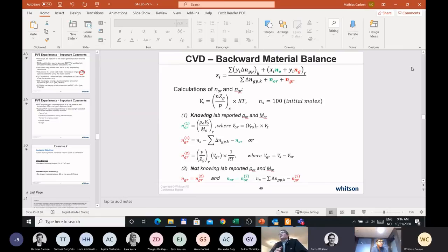So as soon as you get that equation of state, you can just finish tuning. You can just change the temperature for that sample at the bottom to a different temperature and predict the CVD, all the PVT properties at the, let's call it the right temperature. And likewise in the middle and at the top. So I myself would say it's not a critical issue.